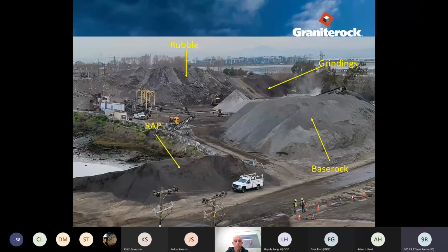So Ed asked a good question about how you address the infiltration of paving fabrics. For us, it depends how big it is. If it's small pieces, we have a process we use to remove the fabric. Sometimes you just get rolls of the stuff and you can't get it all out, and then you can't make RAP out of it. It ends up in your base rock pile, or a non-spec base rock pile. If it's significant, we do our best, but when it gets really significant, you can't put that material back to an asphalt plant.